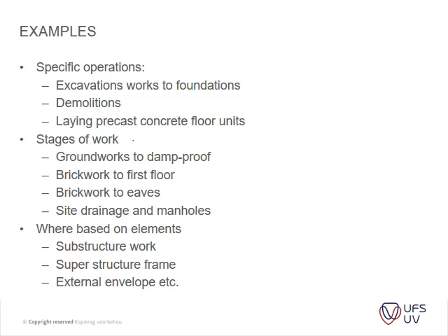And then we're based on elements. You can have your substructure work, superstructure, external envelope. You can structure your method statements in any of these three ways, but it's just to keep a logical flow of it. What the guys usually do, what I've seen and what I usually ask for, is on your program, do your method statements in accordance to your program. So for instance, your excavations or your site clearance, start with your site clearance method statement first, and your excavations first, and so on. Okay.